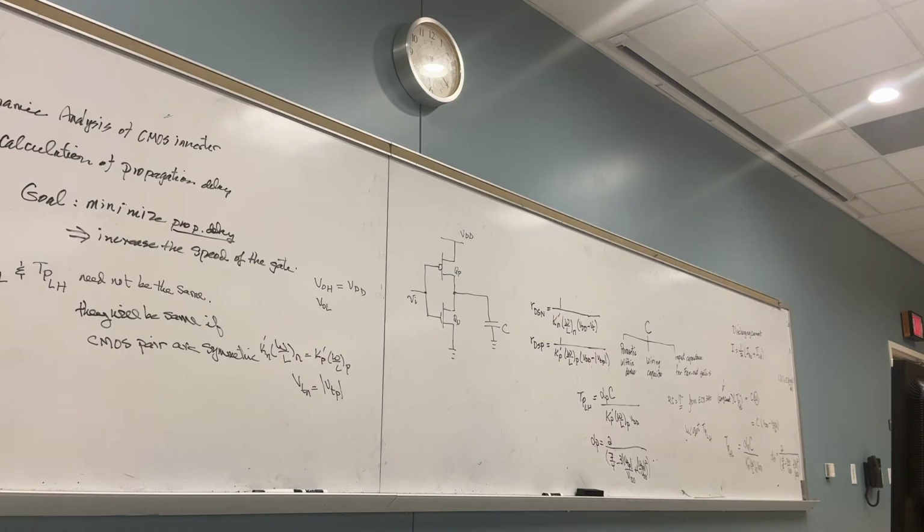You lost me? Why is there power dissipation during dynamic operation, during the switching? There is current passing through the transistors. Otherwise, how will the capacitor charge and discharge?